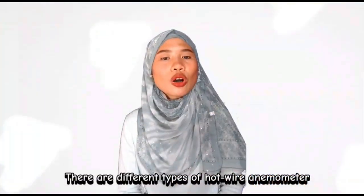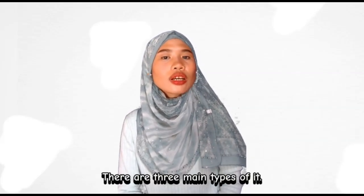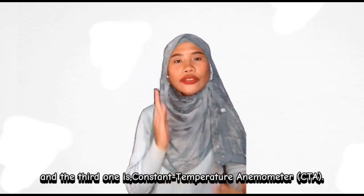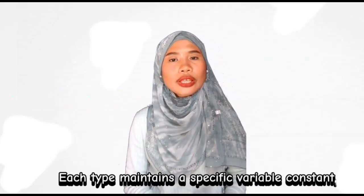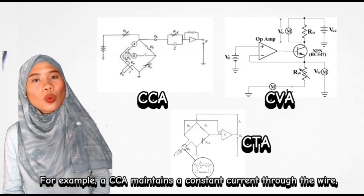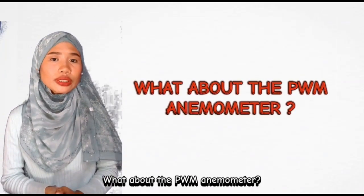There are different types of hot wire anemometers, and there are three main types. The first one is the constant current anemometer, the second one is the constant voltage anemometer, and the third one is the constant temperature anemometer. Each type maintains a specific variable constant, which influences the voltage output of the device. For example, a CCA maintains a constant current through the wire while the CTA keeps the wire at a constant temperature. And what about the PWM anemometers?